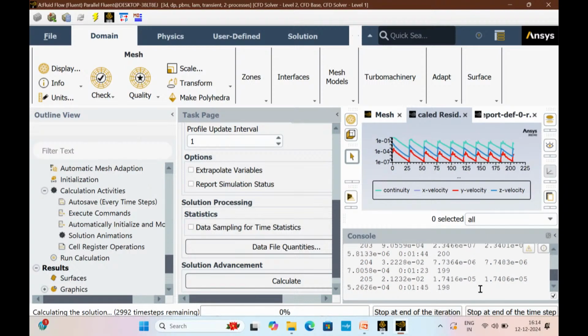Yes. So it is better to prescribe the maximum iterations per time step to a higher value, even if it will not take all of them. But if you prescribe 10 to the power minus 6, then I think it will go up to at least 60 to 80.